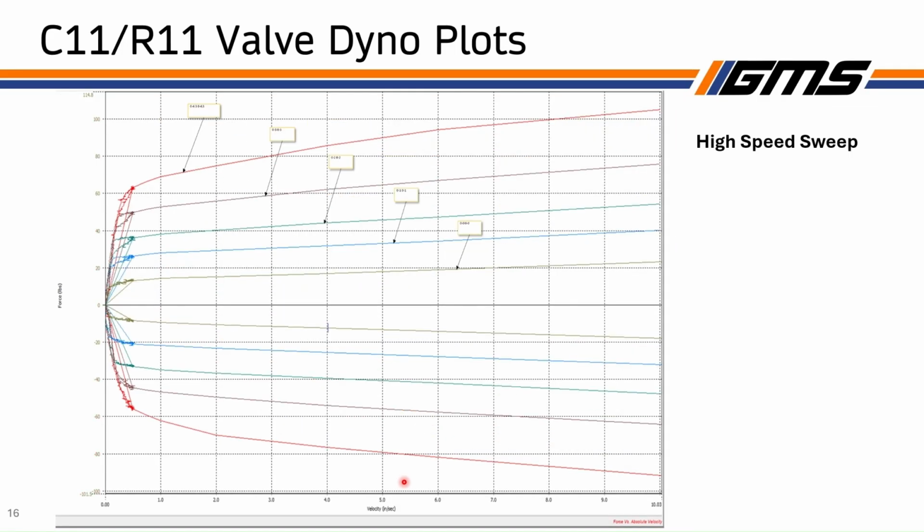They also plot the coefficients, or they give you plots of different high speed settings. So here they make the low speed dampers as stiff as they can go. And then they try out different high-speed settings, so 4.3 turns, 3 turns, 2 turns, 1 turn, 0 turns. And you can see that the high-speed adjuster actually doesn't really change the slope of the high-speed region. It does a little bit for this one, right? It's a little bit of an outlier. All it really does is it changes the threshold at which this high-speed region is going to open up.